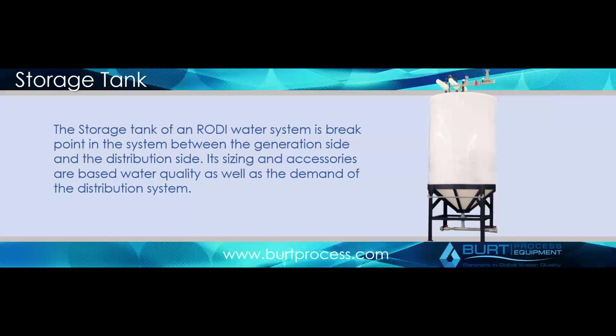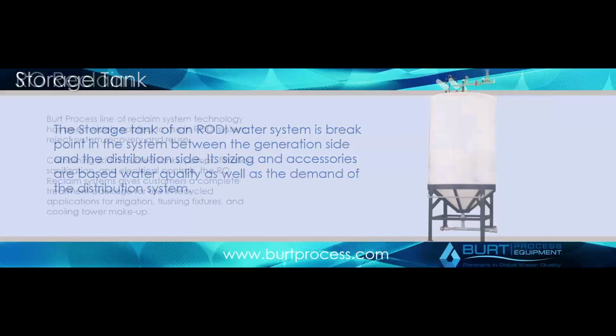They may even have things like nitrogen blanketing on them, and they have a vent filter, 0.2 micron hydrophobic, which is designed to prevent any kind of particulate from entering them when the tank is going through either a filling or a vacuum process, when they're pumping down. So essentially, you're trying to create a clean environment here as you have that filling and distribution and recirculation going on within your actual system.